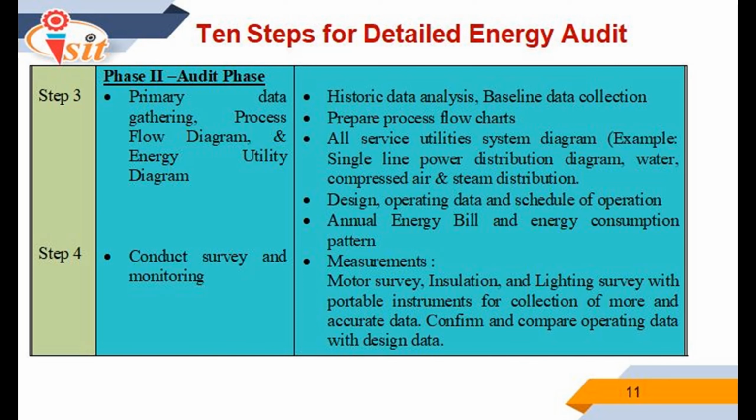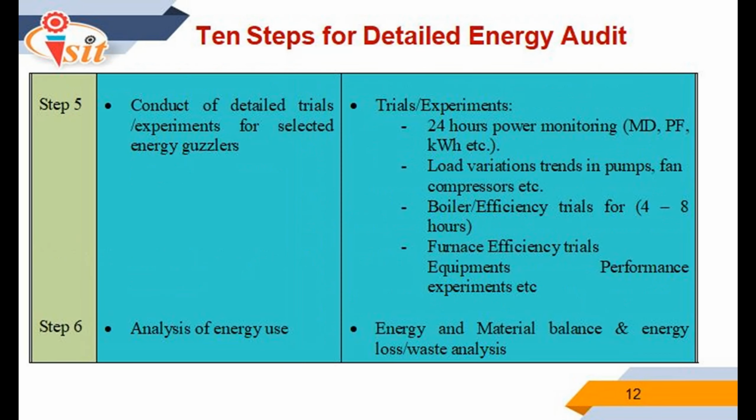Step 4 is related with conducting survey and monitoring. It is related with the measurement of motor survey, installations, and lighting survey with portable instruments for collection of more accurate data. Confirm and compare the operating data with the design data. In step 5, conduct detailed trials and experiments for the selected energy usages.